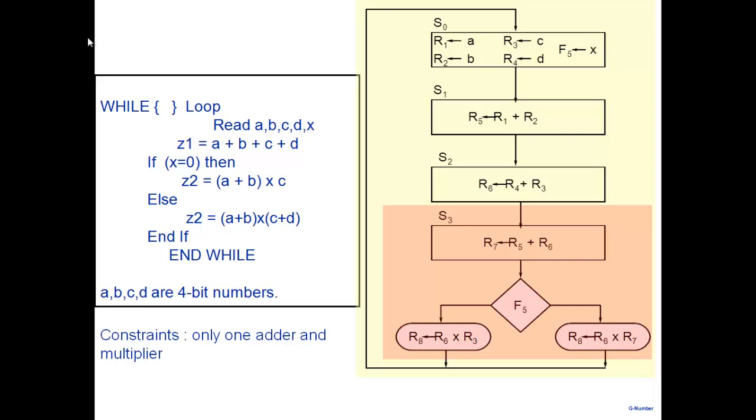Now the shift and add algorithm depends on testing the bit, whether the multiplicand bit is 0 or 1, and for the different bits you will do different operations. So I can take a shift and add algorithm or any other algorithm now. With this available to me, depending on testing some condition and doing one operation or the other, I can now execute any particular algorithm in these ways. I leave it up to you as a homework problem to construct the data path and the controller and finish the design.